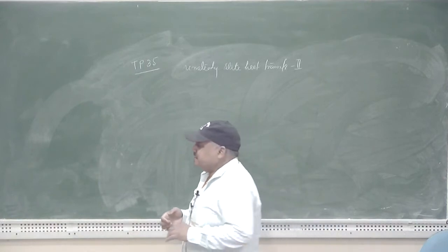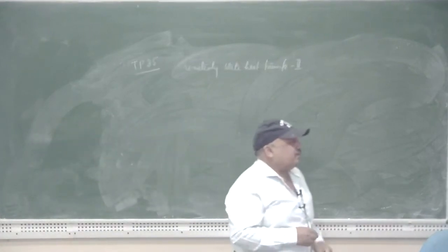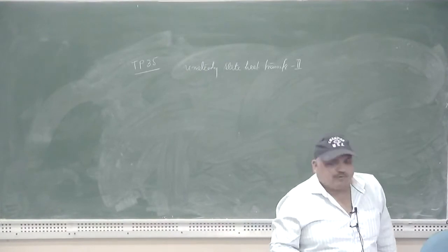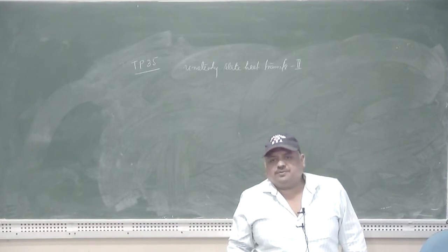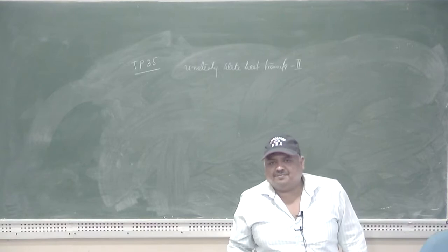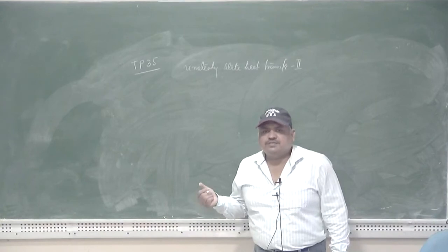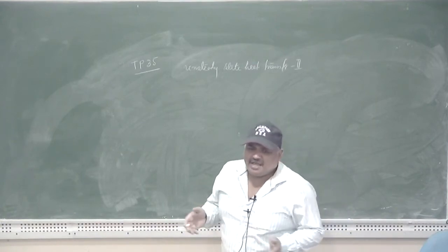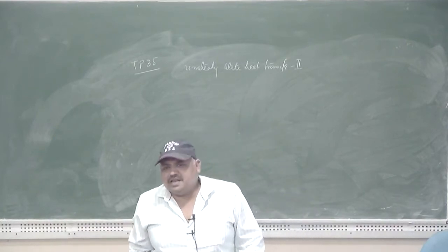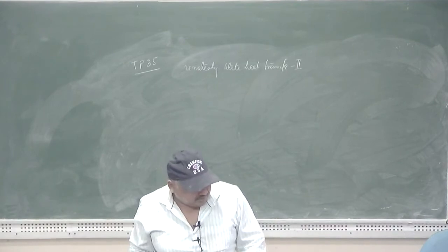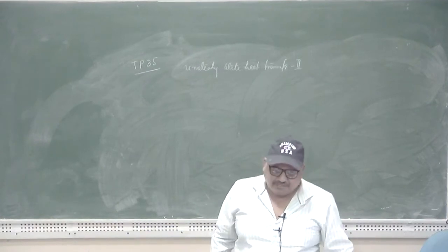Such things are of immense practical importance, as you might have gone through in the practical classes on the response of a thermocouple, in which you have to calculate the response time and determine the time constant of a thermocouple against a unit step change in temperature, and also the sensitivity of this thermocouple. All these things can be derived or understood by utilizing the lumped heat capacity analysis. So let us try to deal with all these aspects in today's class.